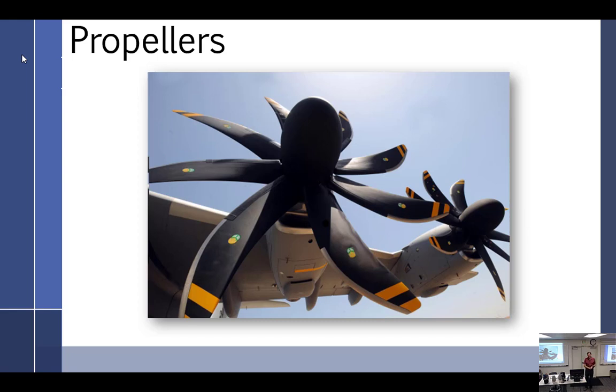And once you realize that, you suddenly realize why constant speed propellers are so much better. Because a fixed pitch propeller is really only designed for one forward speed at one RPM, and the airplane is not designed for one forward speed at one RPM.